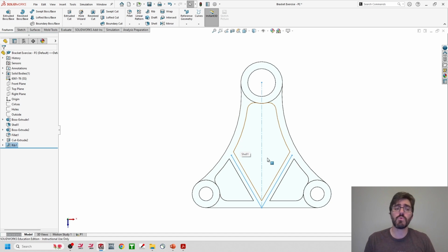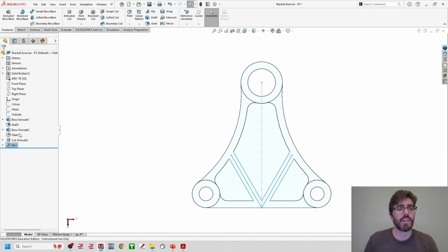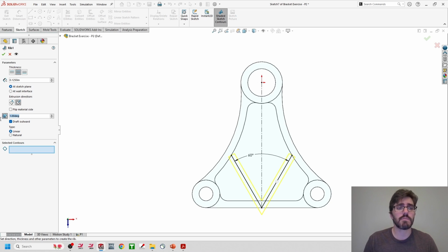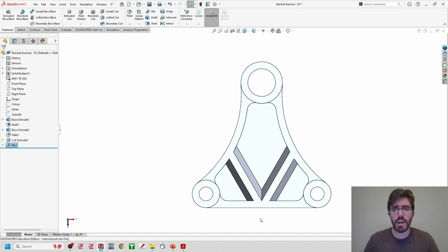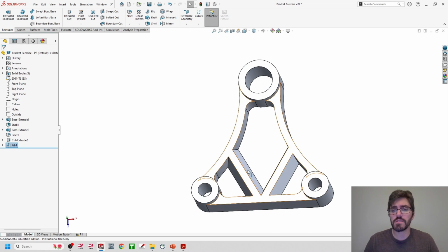So this is a really useful tool, especially if you're trying to do plastics or other mold components. And speaking of that, you can right click on this feature, and I'm just going to show you a bad example so you can just sit back and relax and watch. As I go back into the edit feature of the rib command, I can turn on the drafts, and I'll use a pretty exaggerated example, but let's say I go to 15 degrees. Look how easy it was to create drafted walls at 15 degrees from that simple rib command, only using maybe 2 sketches or 3 lines, 2 solid lines.